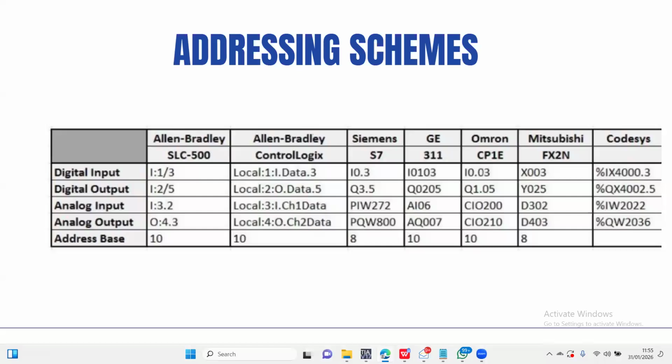I watched the videos, and figured out this is the kind of programming cable you need, this is how to download to the PLC, and you write a simple program, X0 to turn on Y0. The timer works this way, similar to Mitsubishi. So once you know two platforms, I would say it is very, very easy to learn a third one.